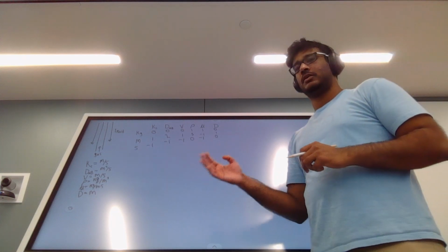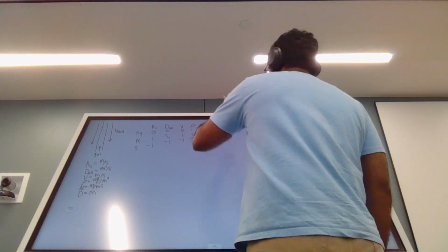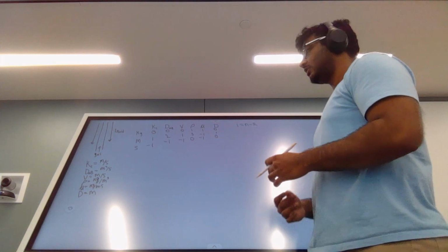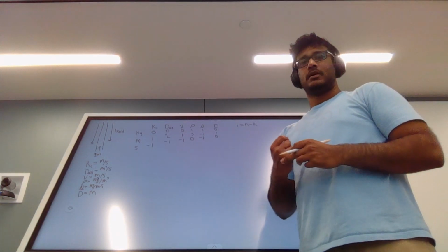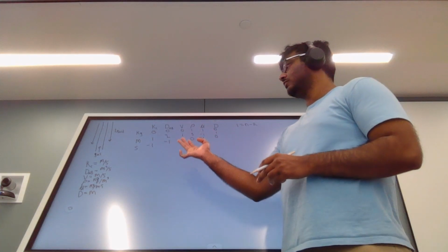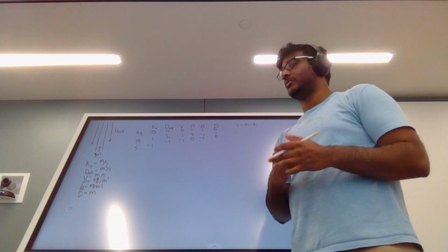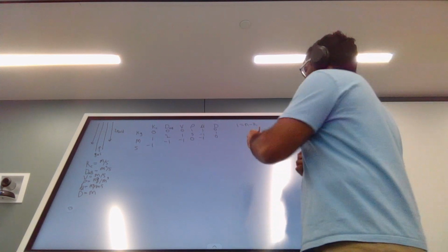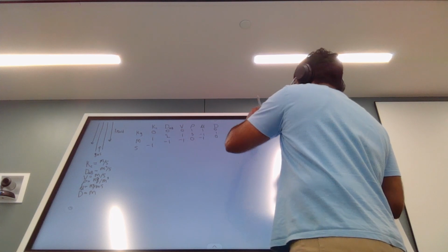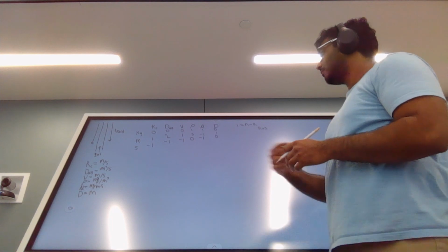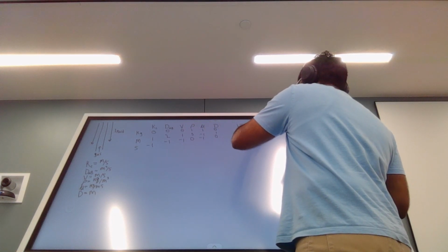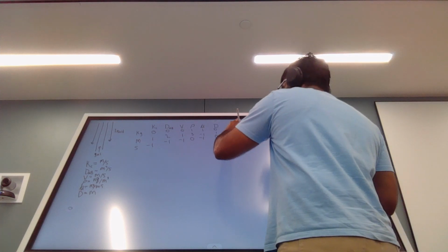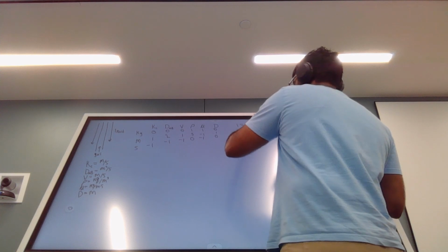So since we now have that in place, we're going to use the equation i equals n minus r. i stands for the number of dimensionless groups, n stands for the number of variables that we're considering, and r is the rank. To find the rank, we type this into our Python code using the linear algebra function from NumPy. That has already been done for this problem, and we know that the rank is 3. So r equals 3. And since we have 6 variables, n equals 6. Now we can say i equals 6 minus 3, which equals 3.